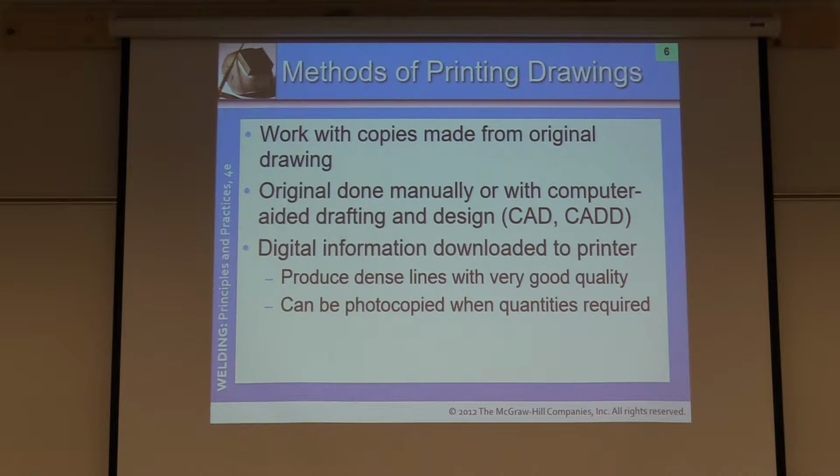And then 29.3 shows you the standard drawing sizes in SI units. These sizes will be encountered when working on prints coming from outside the U.S. The A0 size will be the largest, while the A4 size would be the smallest. These letter-number combination codes may appear on the specification, so you must have an idea how large the print will be. And it's important that you understand both, not just the traditional English version, but the metric, the SI units as well. Okay.